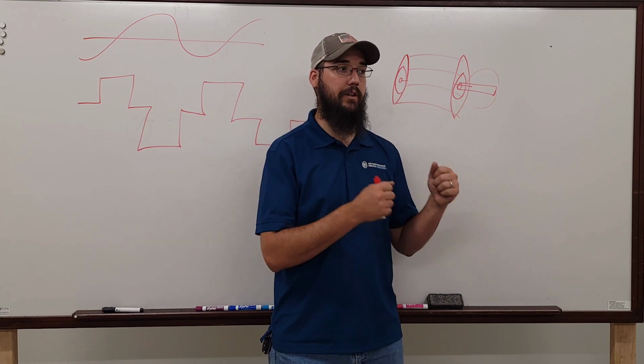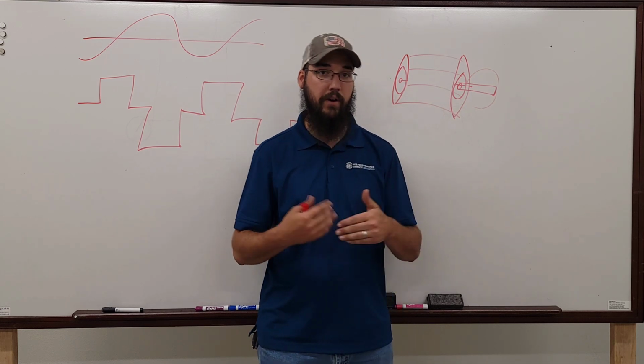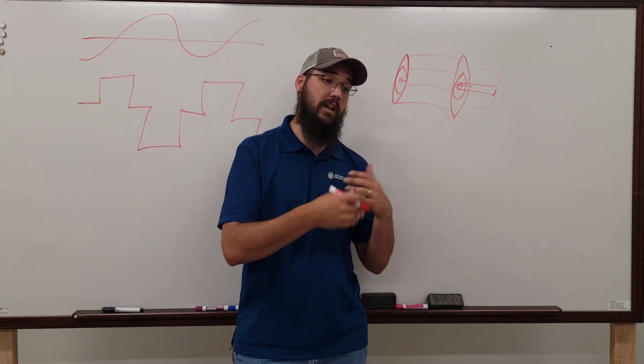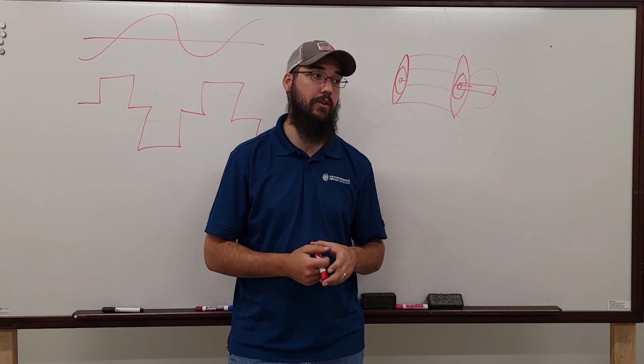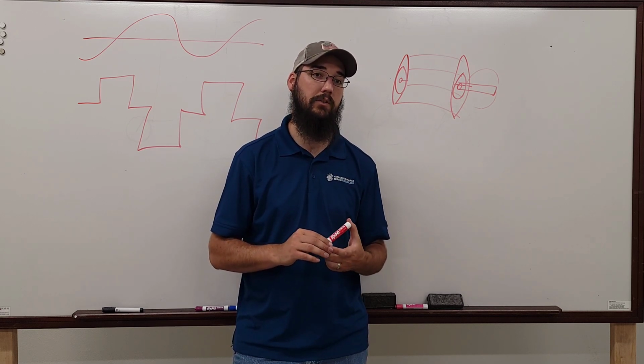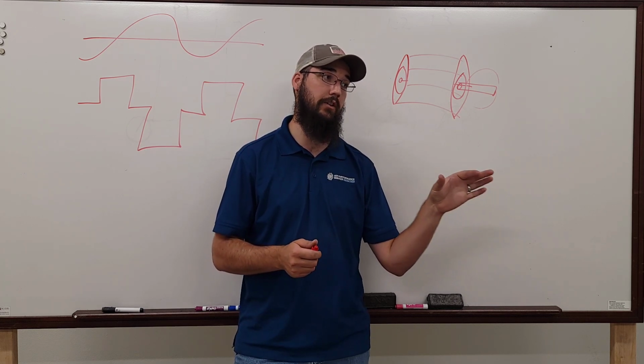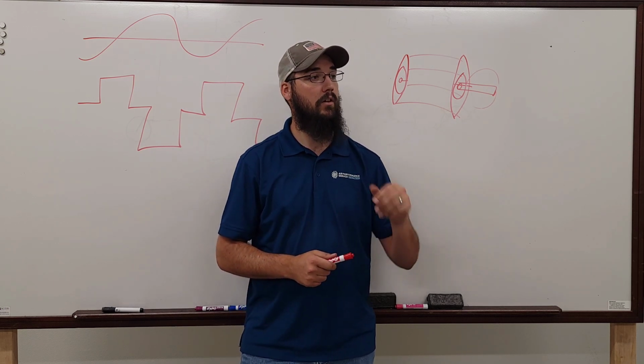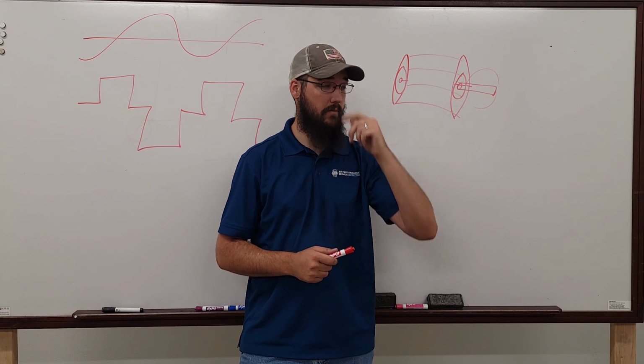Most of your factory-done motors that come factory shaft grounded will have a brush kit or something installed internally most of the time. Those are the ones I see, and they'll usually actually say that, has a brush ground kit or something along those lines.